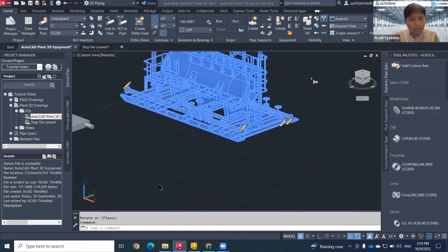So I have two questions. The first one: can we use this Plant 3D file and open it in Revit? Right, this is a mistake that people make. Plant 3D is very detailed software for creating fabrication for piping and isometrics. In Revit we are only able to attach or import CAD files, import or link. So if you want to insert your Plant 3D into Revit, that will be the biggest mistake. Normally people will use Navisworks to integrate, not Revit.